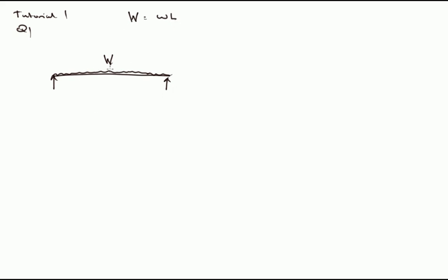So we've been given the total load of W, so R1 and R2 must be equal because everything's symmetrical. So R1 equals R2 equals capital W divided by 2.